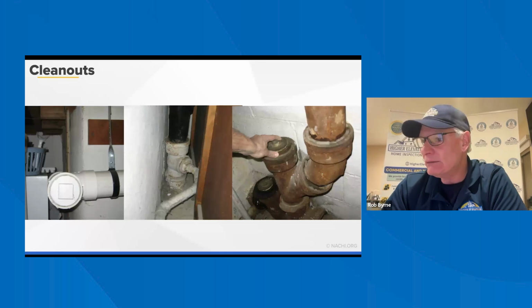Sealed system: sewer ejector pits must be airtight and vented to prevent sewer gases from escaping, and must discharge through a check valve to stop backflow. So what we're saying there is, like the picture on the right, you have a pump, whether it's an ejector pump or a sump pump. The picture with the hand on it with the green, that's a check valve. As the water goes up and gets past that point and the float stops it from pumping, the water doesn't go back down into the pump system and keep short cycling. So that'll prevent the water from going back in. And when the pump comes on, it's a one-way valve. It'll push it up and out and you're good to go.